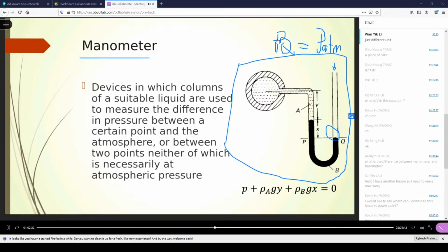Now this column, this water, all these fluids are at rest. Therefore, you can work out a force balance. We know the pressure at this point. Therefore, we will be doing a force balance along the PQ direction. The areas of the two rims are the same, so force balance means pressure balance, so pressure equality or pressure equilibrium.